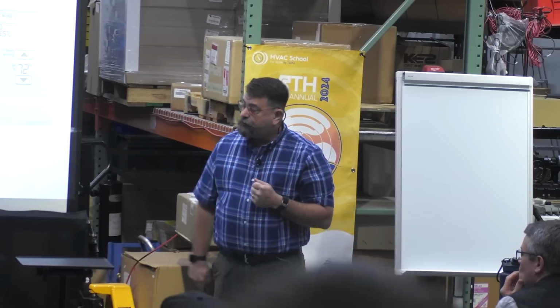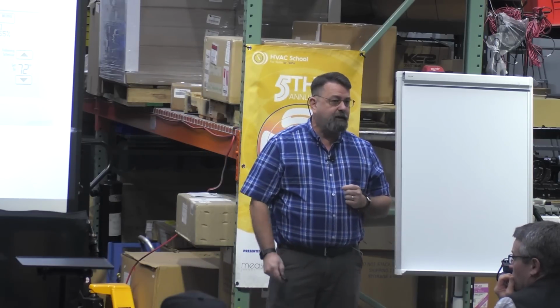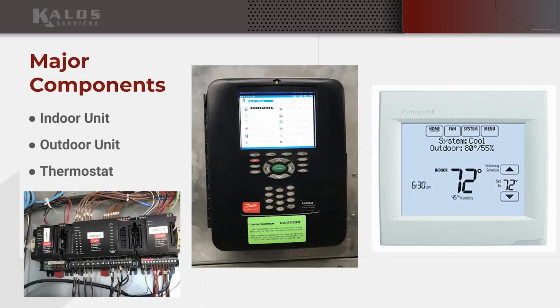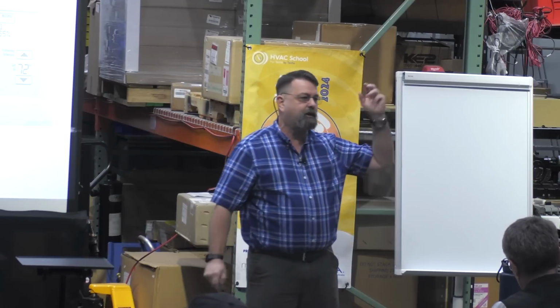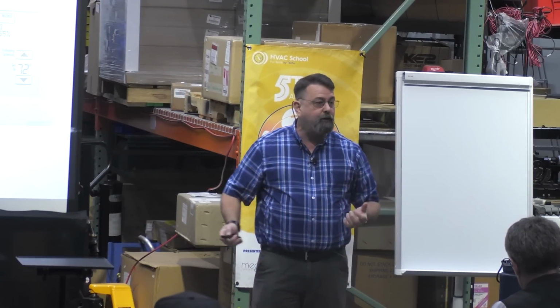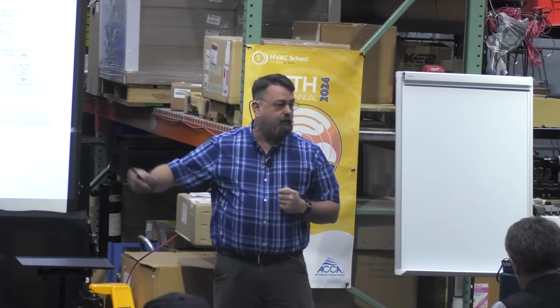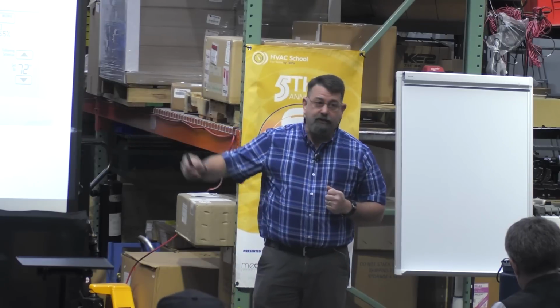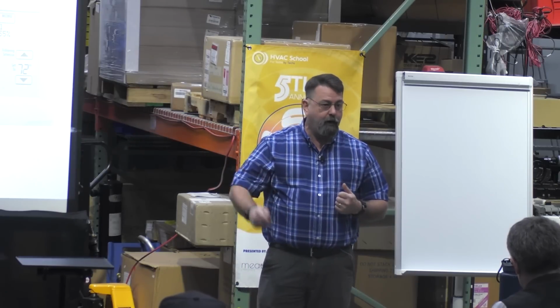Well, in supermarkets, guess what? I'm going to do exactly the same thing. I'm just going to do a lot more of it, all right? So right there's my big decision maker, okay? And then over there on the side, you can see I've got modules. My modules are going to have inputs. They're going to have those temperatures from the cases coming into them. They're going to read my suction pressures. They're going to read my discharge pressure. All those values are going to come in to modules, and then my brain's going to make decisions based on those. That's my program.